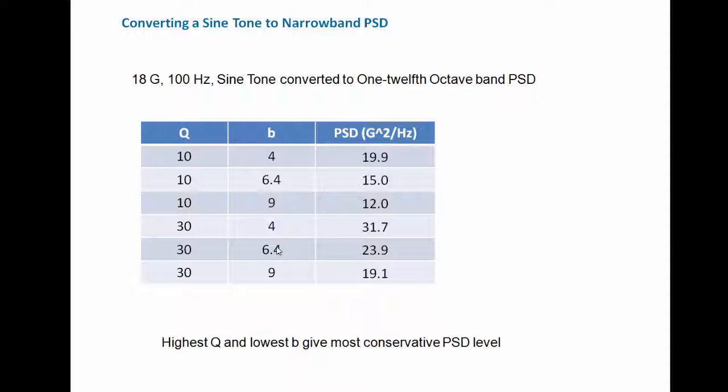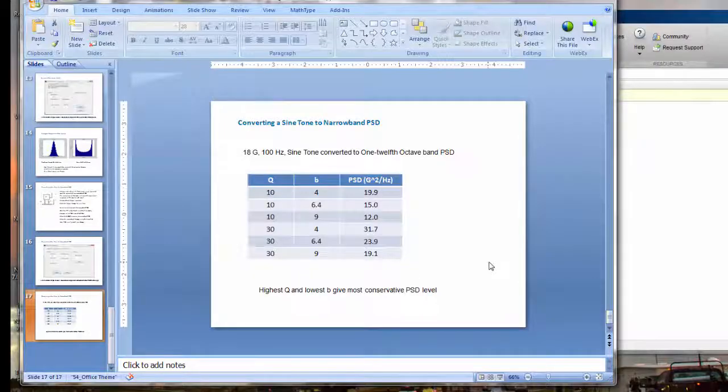And I do have some information on my blog about fatigue exponents. Again, as I started to mention earlier, Q, according to my colleagues, is the biggest uncertainty factor, but in fatigue analysis, the effect of B is an even greater uncertainty factor, because that takes our amplitudes and raises them to an exponent.